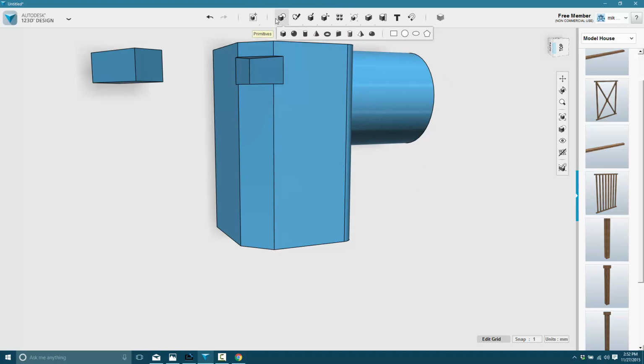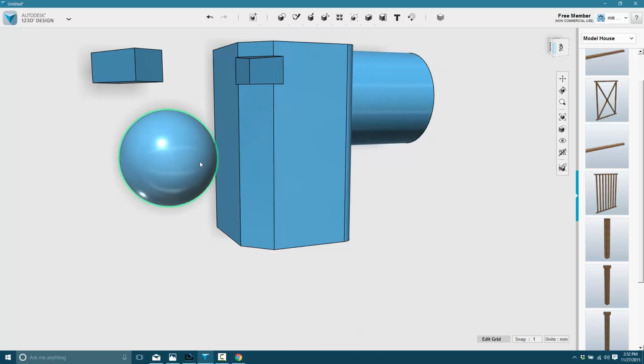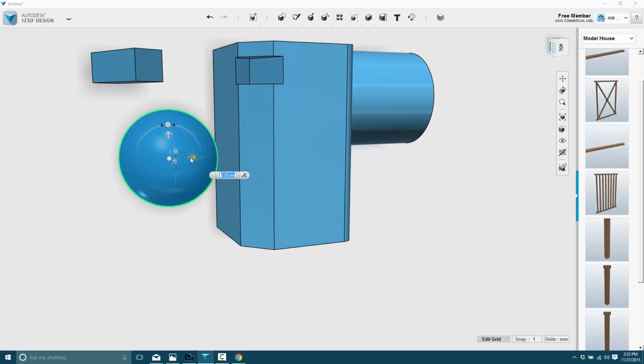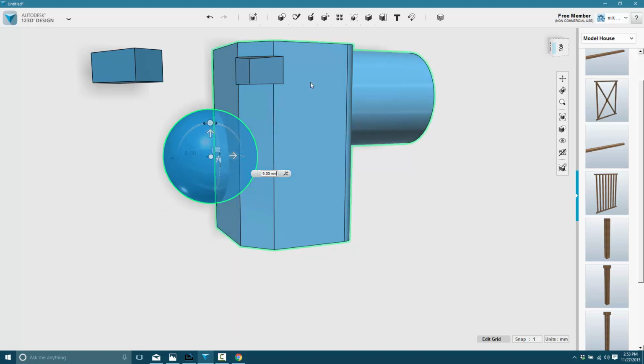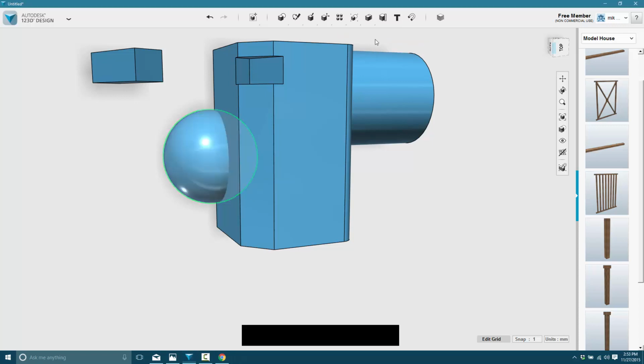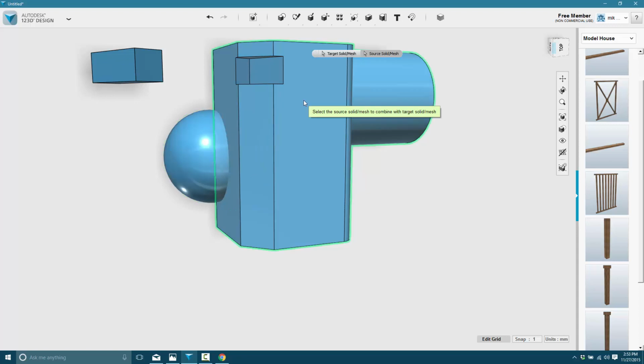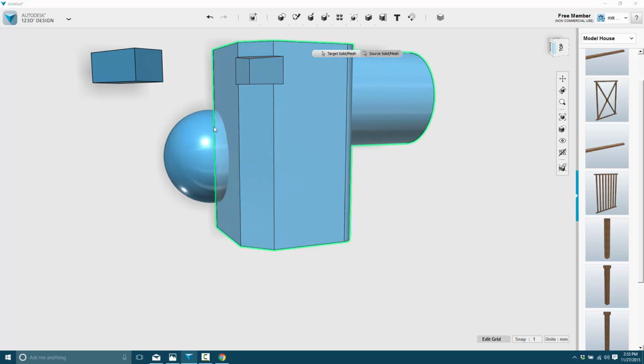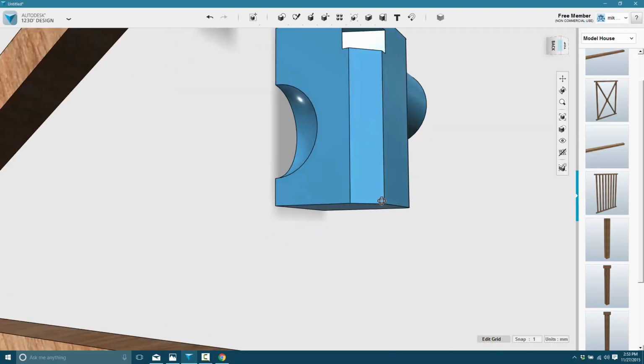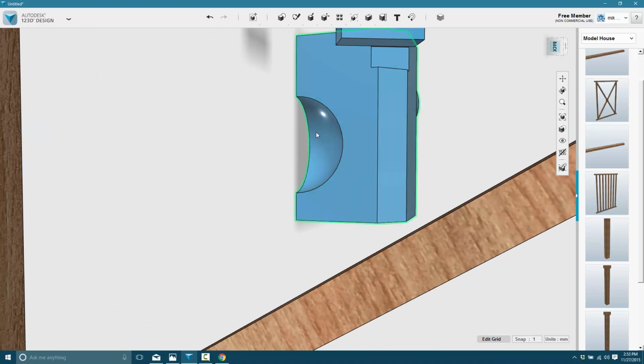And if we come back, so far I've just used square surfaces, but we could just as easily use a sphere to make the cut. So like so. I'm going to move you into the surface, and let's do an intersection cut. Actually, we'll do a subtract. No, I got that backwards. So select target, is this guy? Source, this guy. I might do this backwards. All right, target, source, enter. There we go. So you see now we've got nice, smooth, rounded curved surfaces as such.